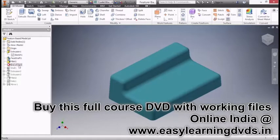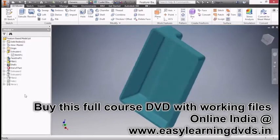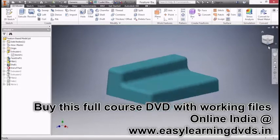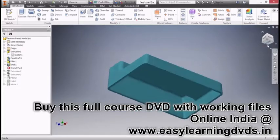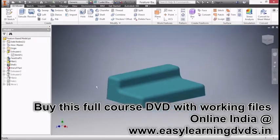And then we have a shell. Well, what did the shell do? I don't see anything. Well, it's because it's on the underside of the model. If I rotate this, you can see the bottom side very easily. Rotation in the software can be done in numerous different ways, just as a little tangent here. But if you're having trouble with the rotation right now, just go ahead and use this cube that's in the upper right. If you click on the home icon, this little picture of a house, that'll take you back to that standard isometric view.